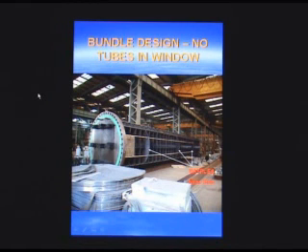What that does is that the first baffle, you'll be flowing across the bundle in this manner from right to left, and then the flow will proceed down the shell until it encounters the next baffle, or let's say there's a solid plate further down that will prevent flow in this area, and that will redirect the flow back across out of this section. It will turn around and then go back across and right in this area.